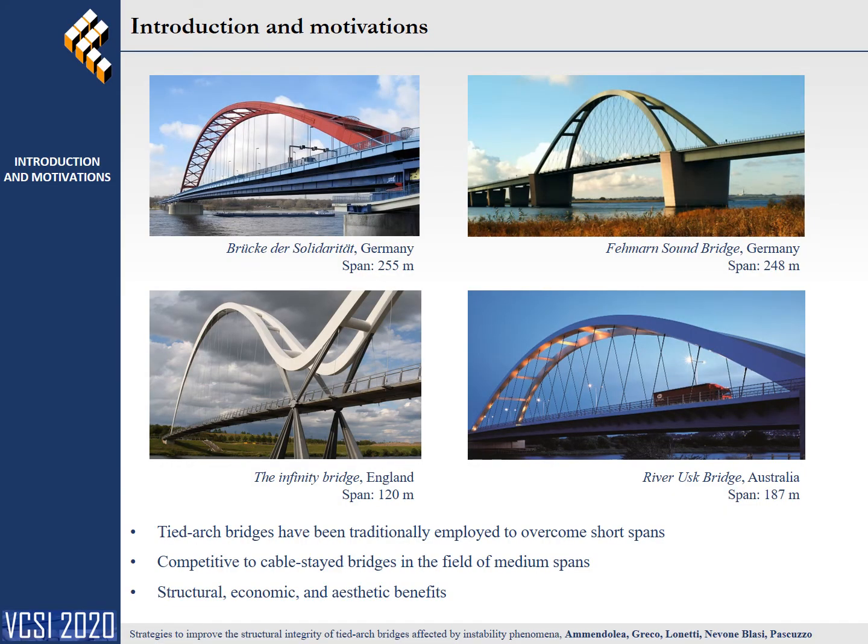Tied arch bridges have traditionally been employed to overcome short span lengths. However, during the last decades, these structures have become very competitive with cable-stayed bridges in the field of medium span lengths, and probably they will be an effective solution to overcome long spans in the near future. Tied arch bridges ensure relevant advantages from both structural and economic points of view. In addition, the structures are aesthetically attractive.